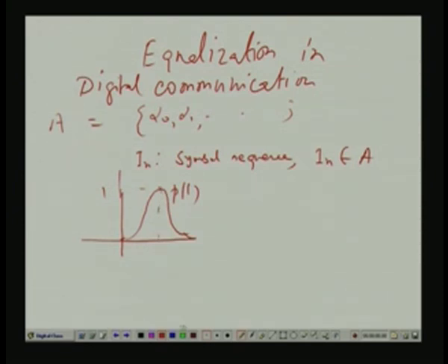Now, suppose with this pulse, you multiply the pulse by I0, so the height will be I0. You trigger it here and measure it at the receiver at this point of time, say capital T. But since you are transmitting fast, you will not wait up to time capital T. You might trigger the next pulse at tau and multiply the pulse by I1; at minus tau, you triggered another pulse, I minus 1, and so on.